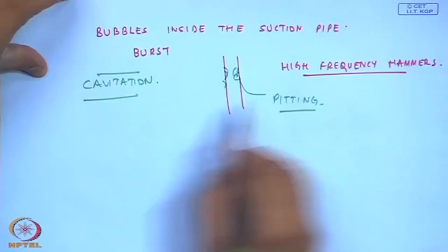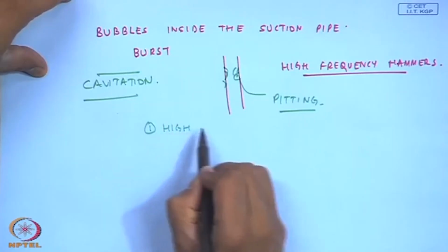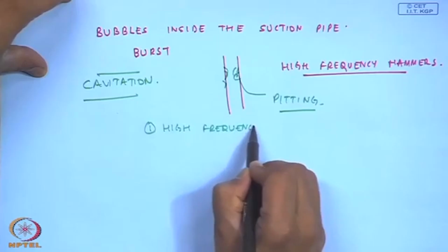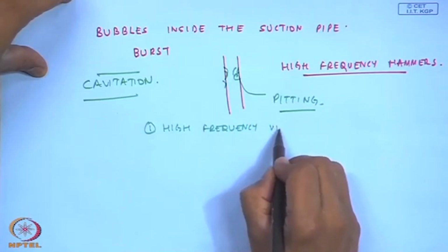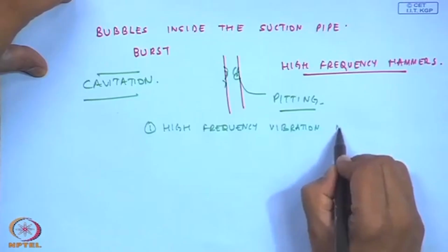To monitor cavitation, because it is high frequency, we can always have high frequency vibration monitoring.